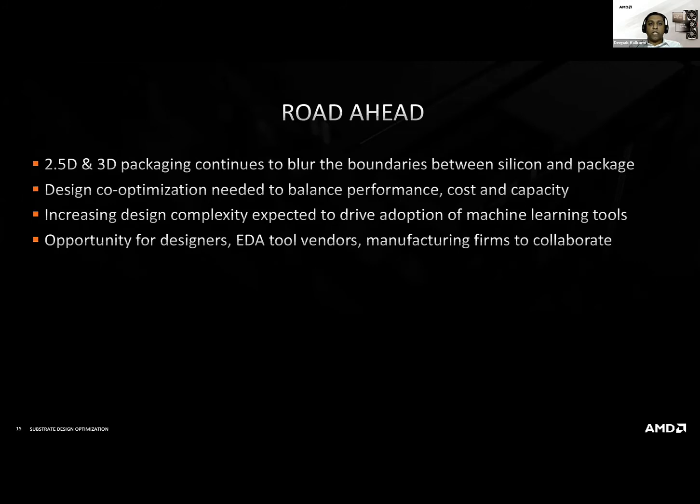And so the increased design complexity that this brings in of understanding what is needed from a silicon floor plan perspective, what is needed from a package floor plan perspective, and how do we co-optimize all of that really lends itself to machine learning tools. These are not rules that can be codified, but essentially methodologies that need to be developed.